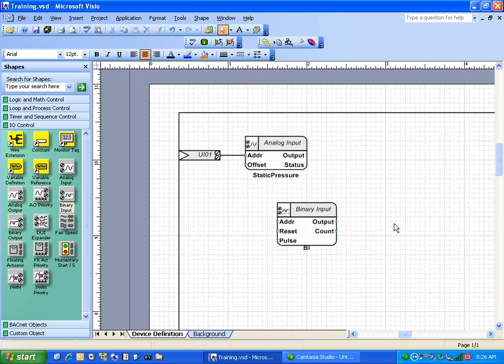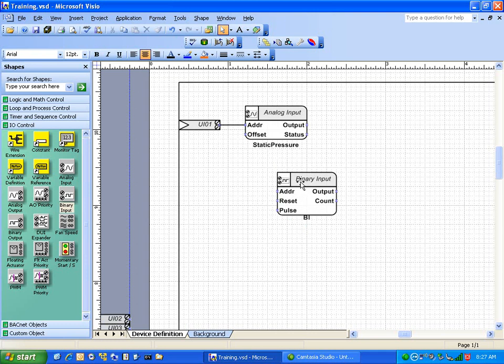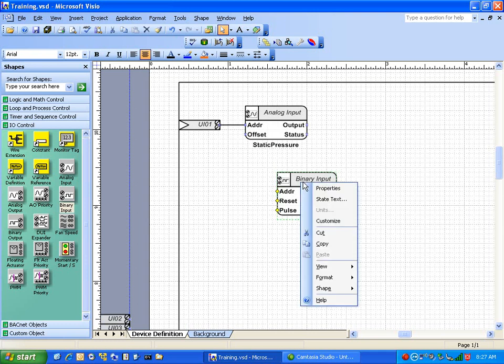The other thing you can do with binaries, which is very helpful at this level, if you are aware of it: sometimes you get engineering drawings, and you'll see that maybe they have some type of sensor giving us an alarm contact from a third-party device, and the engineer simply doesn't know what its normal state is. Does on equal alarm or does on equal normal? You just don't know that up front. And, unfortunately, it is a guessing game.